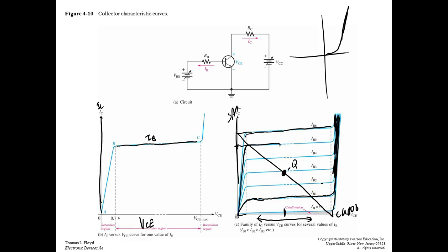If we operate it in that region as an amplifier, then we could move it toward cutoff and saturation, and it still wouldn't affect the collector current, right? Does that make sense? Now these, we're not going to use as much. Like I said, they don't give us these much. We can get a rough feeling by using the beta of the transistor, but then our lines would be straight across. Using a straight line is not going to give us a big problem because it only has a slight slant anyway, right? You understand? So this is why they don't give you collector characteristics first.